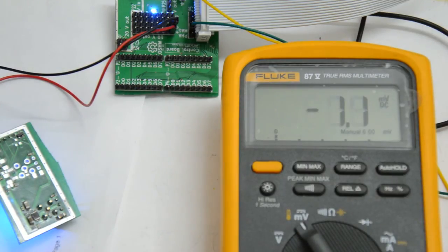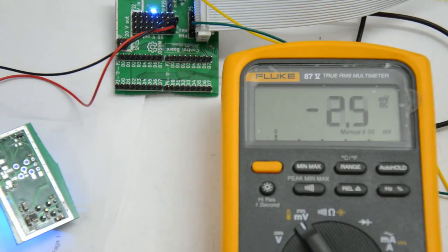So I guess what I'm measuring here is some sort of leakage. And of course, with these impedances, that is going to depend hugely on what kind of meter you're using and things like that. So I'm not too concerned about that, and I think that this test is just to see whether you've got your input shorted to either of the rails hard, and that's not the case here.